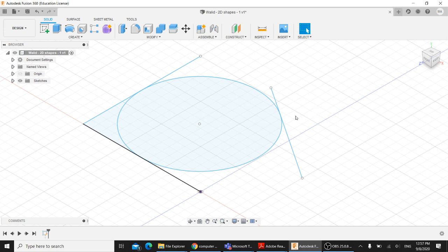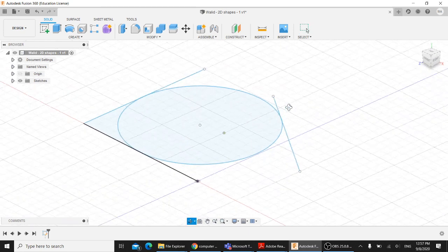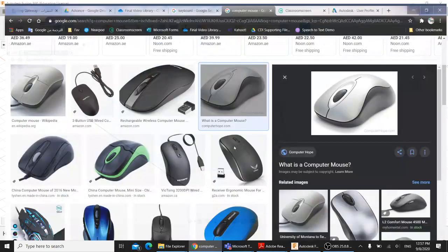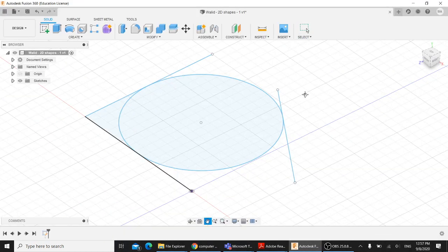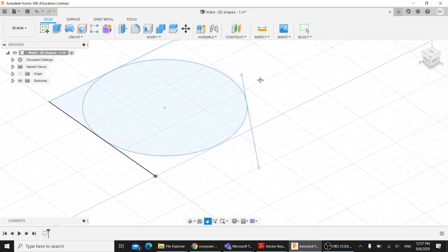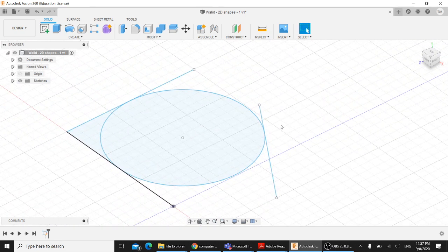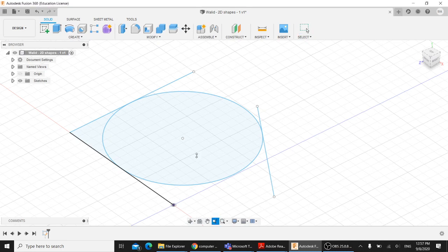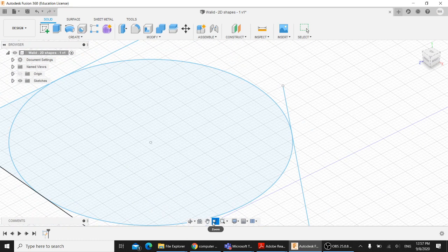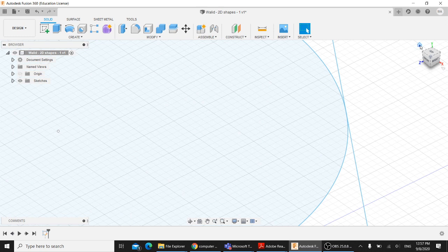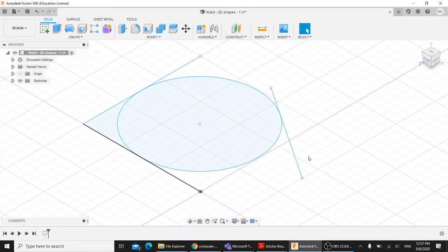What if I want to go maybe to the right without changing my view? I want to fix this view, for example. You can press on the scroll alone. Just press over this scroll alone, and then you can move like this without changing your angle. And of course, you can zoom in and out using the scroll itself, or over here from this tool bar. So anytime if you feel lost, just click the home view and it will take you back here.